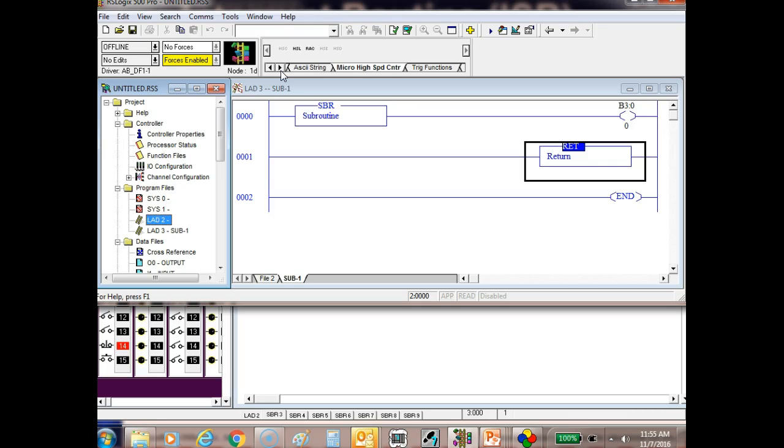It's real easy for us because we're programming in a high-level language, but every time you insert a timer, what it does in the machine language program is it puts a program or a subroutine in there that handles the timer. So it might be 500-600 lines of code, not rungs, lines of code. And then that depends on how fast the processor runs. So that's why we want these extremely fast processors, so we can run those modules real fast, right?